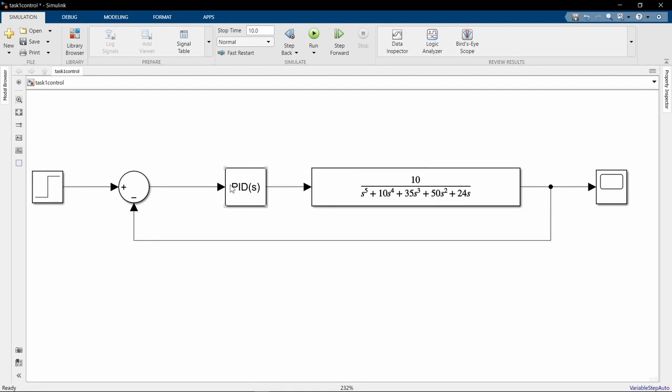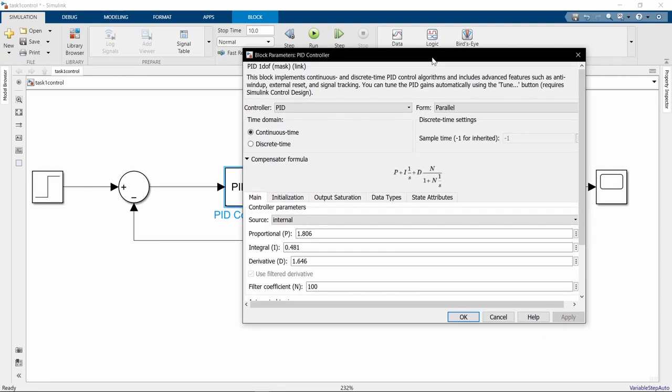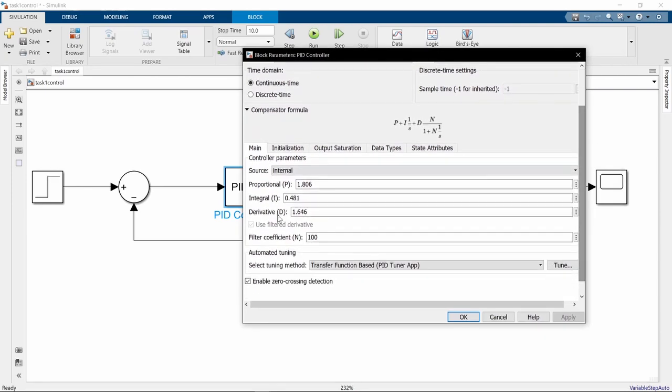The default would be this small, but to fully see the transfer function, just drag out the block and it pops out. Since we are going to simulate a full PID controller, double click the PID controller. We adjust the settings for P, I, and D, and we get these from our calculations earlier.